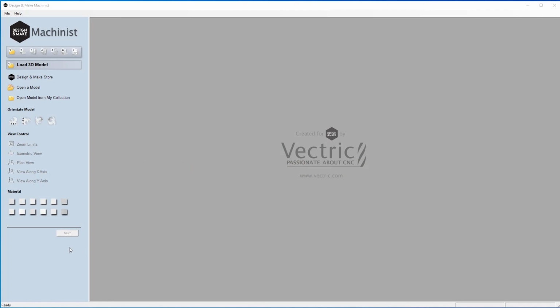Okay, so once you've actually downloaded and installed Design and Make Machinist, you can just double click on the icon on your desktop and it'll open up the software as we have here. And you'll notice that Design and Make Machinist is set up to follow 7 easy steps. So you can just follow from importing your design to creating toolpaths all the way to saving out your design so you can run it on your CNC.